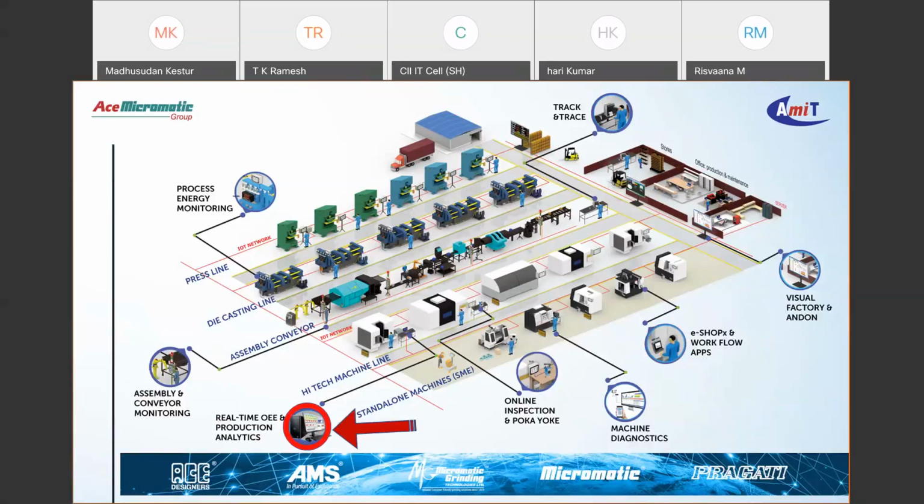So as he starts producing, we monitor OEE from the machine, which comprises availability, performance, and quality measurements. So the product of APQ gives the OEE of the system, and we monitor it in real time so that any problems that occur in the line or the machine can be alerted in real time to the right people. And the follow-up actions that will be taken on these alerts will definitely keep the OEE intact.